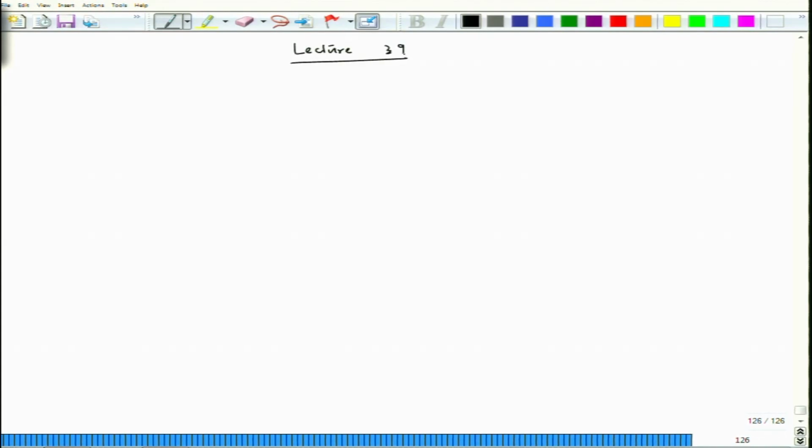So, we are left with 2 more lectures, and in these remaining lectures, we will consider some case studies where corrosion happens in a metallic object, and we will try to understand those corrosion events with the help of mixed potential theory. In the last lecture we saw how this mixed potential theory can explain the corrosion event in the case of zinc in HCl, and then we tried to draw the Evans diagram, which is basically